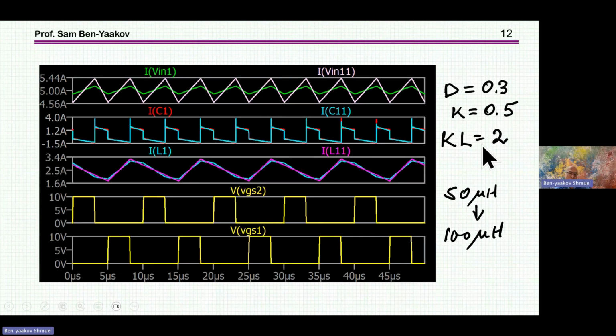And it turns out to get this, you need the inductance of each winding of the coupled inductors to be twice that of the uncoupled. So you lose here. And of course, then you have to do the summation of losing here, gaining there, and see how much you actually gained net in this case.